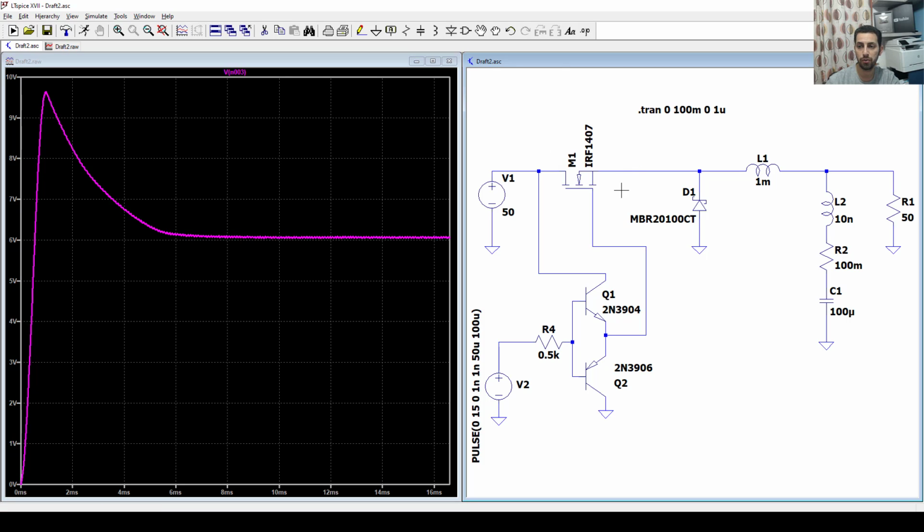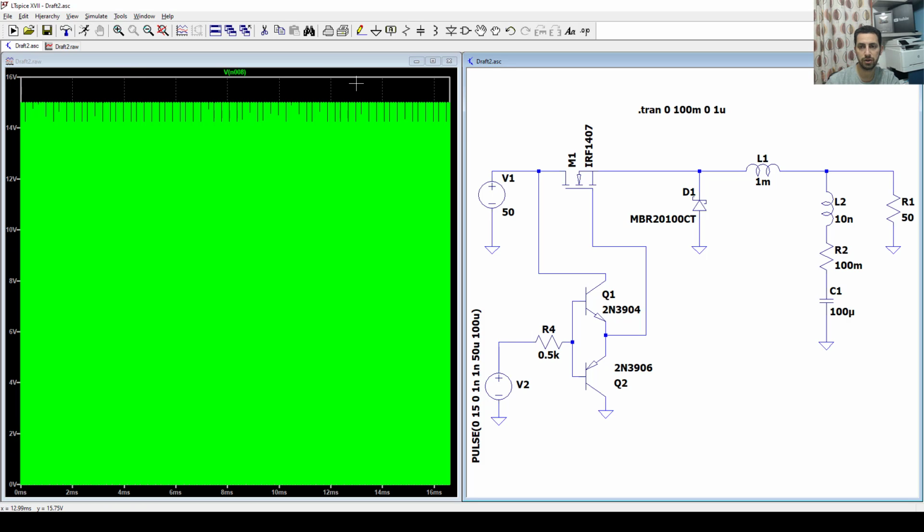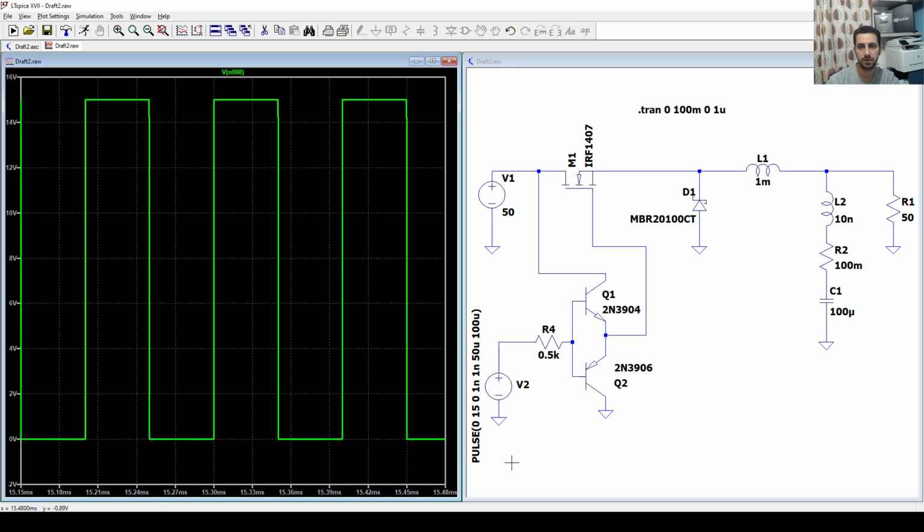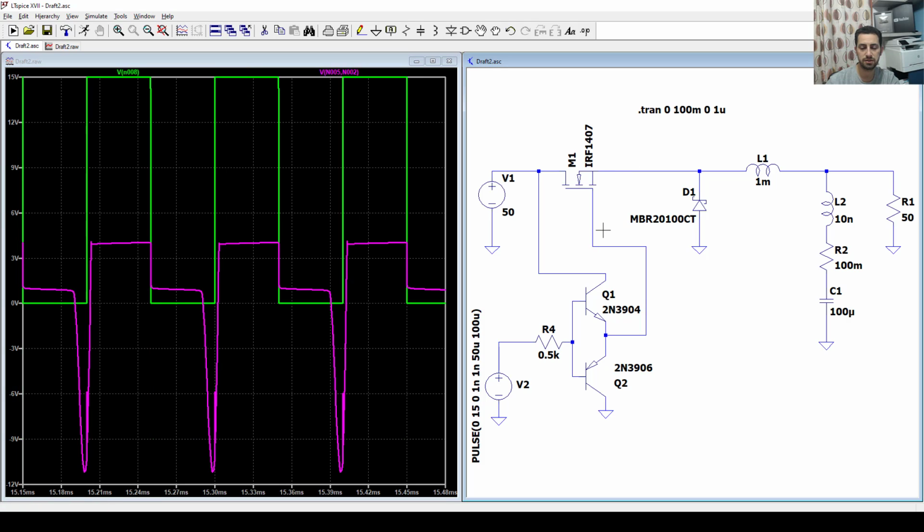So if I look at the PWM pulsation here, and let's also zoom out a little bit, and also the VGS between gate and source. Yeah, look at that. Look at that. So from 0, maybe 1 volt to 3.5 or 4 volt, 1 to 4 volt, it's not enough to turn my MOSFET on. There is still a problem. I can't turn it on.